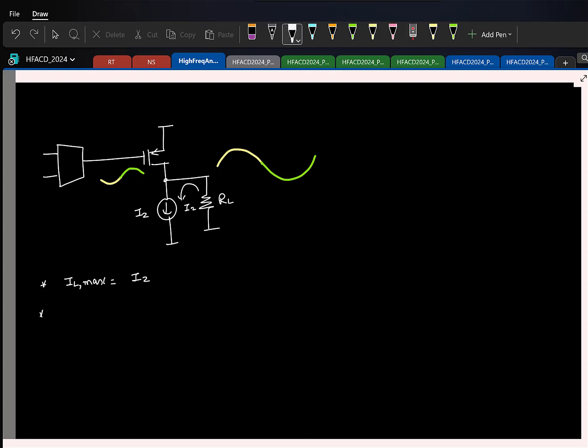So this kind of setup is called a class A bias or a class A stage, wherein you bias the stage with a constant current, right? Here, as you see, there is no issue when the output wants to go higher and higher. When the output is trying to go higher and higher, the gate is also going lower and lower. So this can nicely source a lot of current, but you are limited on the other side, right? But that is not ideally what you want.